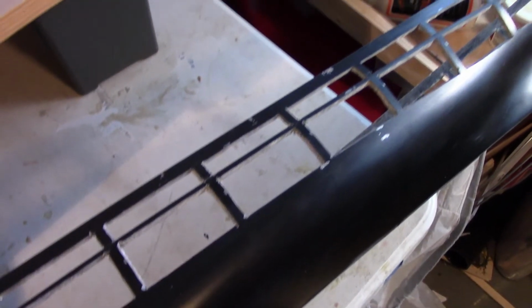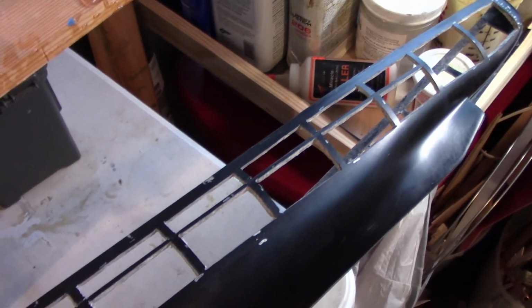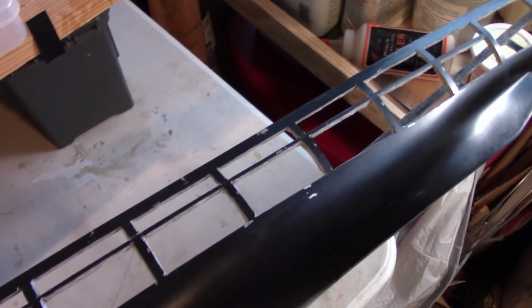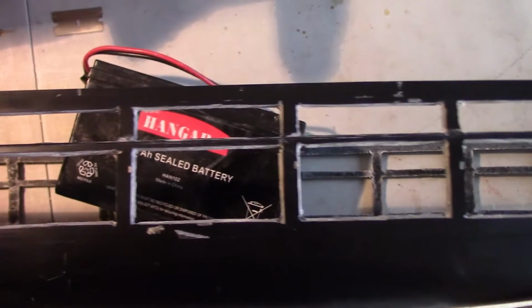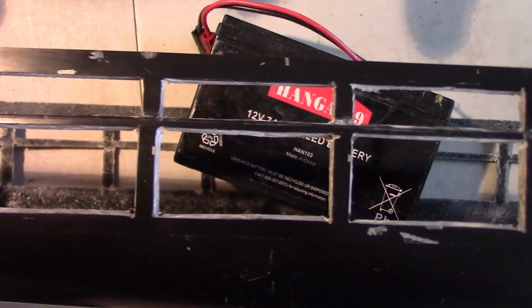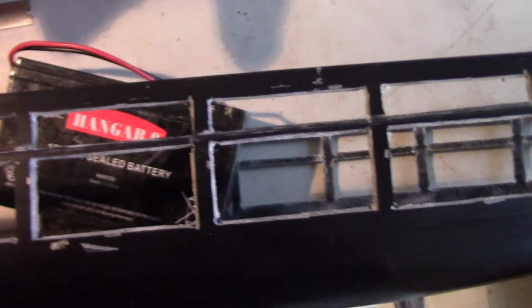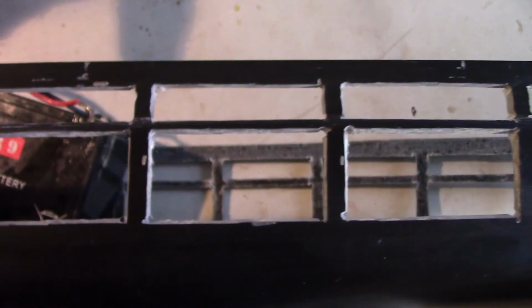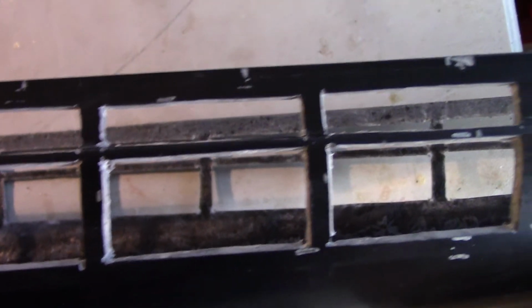If it's a boat that's like a slugger that is going to be taking a ton of damage, then you probably want to err on the side of thicker ribs. If it's like a cruiser, it's really not going to take a ton of damage, then thinner's okay. You can also see the trapezoid effect a little bit on these. You can see it flares out. It's a little bit wider in the back as a result of the angle that I cut them at, and that'll make the ribs and the stringer a little bit stronger.